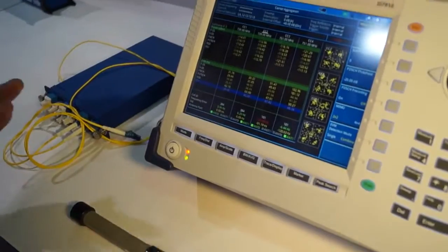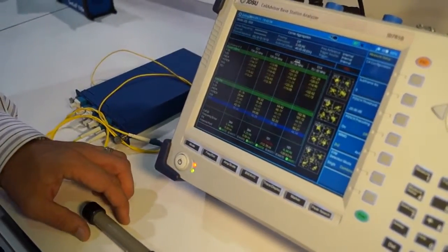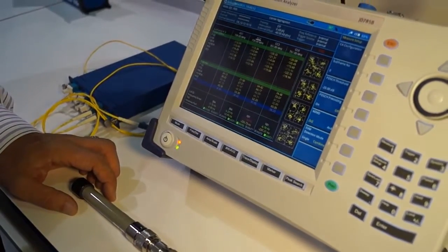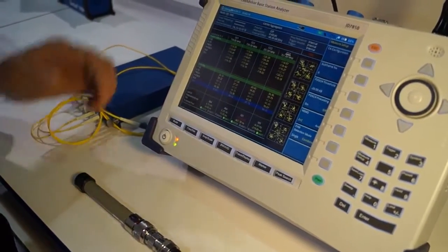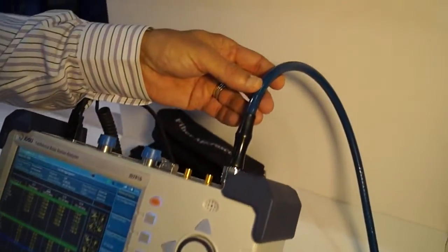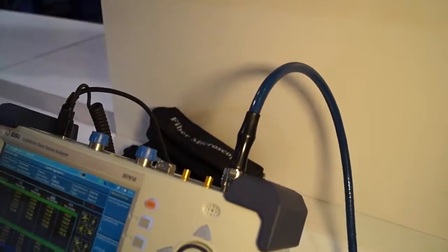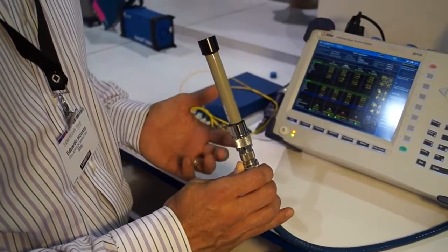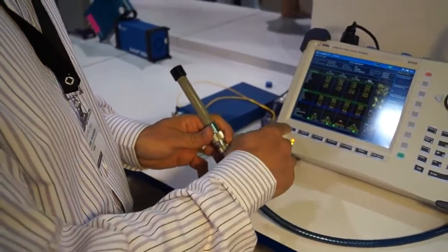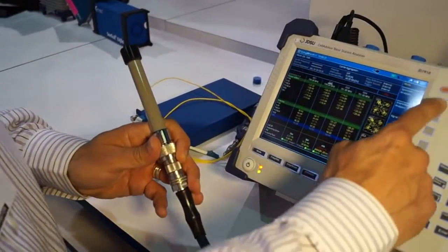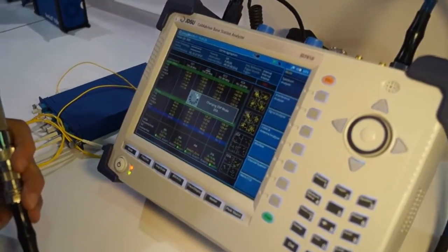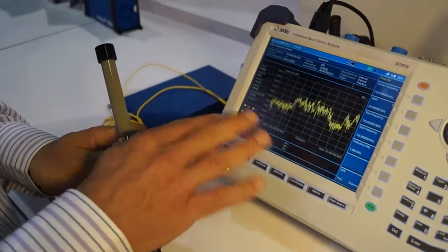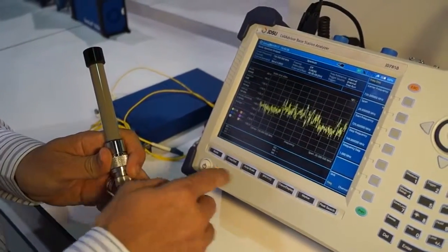Basically, traditionally with old or conventional cell sites, all the tests, mainly as an example for interference analysis, were made through coax. So as an example here, I have a coax connected to an antenna and doing some testing. Now this testing is for LTE advanced, but more importantly for interference, just looking into a spectrum analyzer. And here in the spectrum analyzer, it's looking basically around the signal type and form.